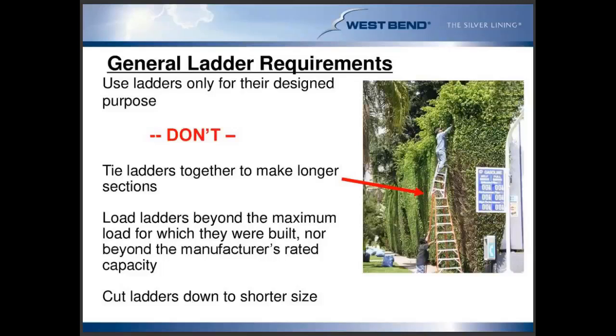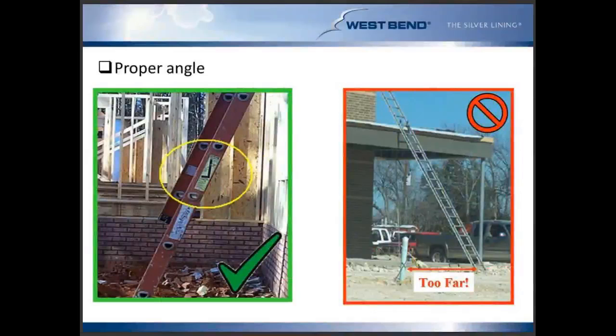While that seems like a good idea, the second we cut that ladder down from its originally designed height, again, it's not being used for its design purpose and likely would cause damage to it. So definitely want to throw caution out there. If that is a practice within your organization, you might want to reconsider, as it could result in a fall injury.